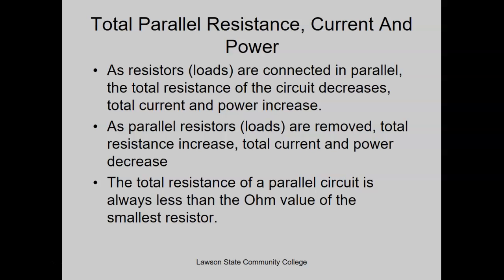The only time a resistor will change value is one of three options. Either your resistor has become open, your resistor has become short, or you've got a potentiometer and/or rheostat, which is a variable voltage, variable resistance device. If one of those three conditions is not met, your resistor will never change values.